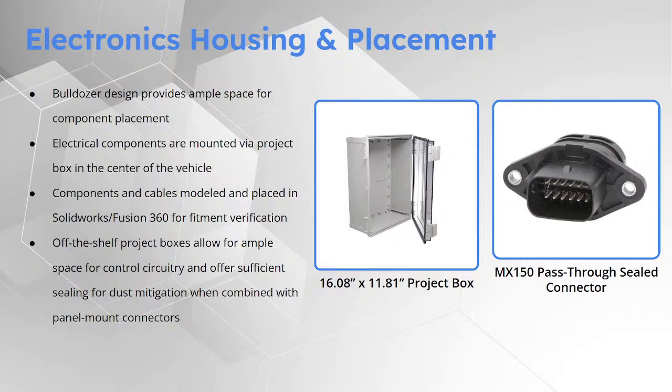There are a fair bit of those lying around between different employers that people have, so probably not something we're going to have to buy, but they do make sealed Anderson connectors too that we're looking into for those 8.33 amps per motor applications. But from what I understand, MX150s are good up to 20 amps themselves.